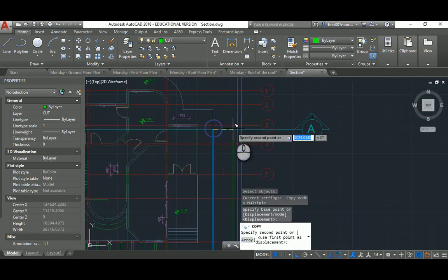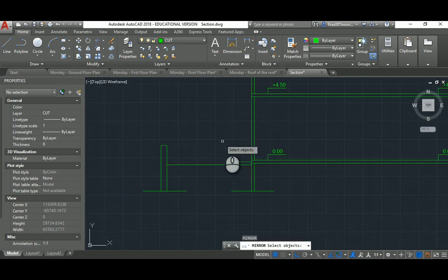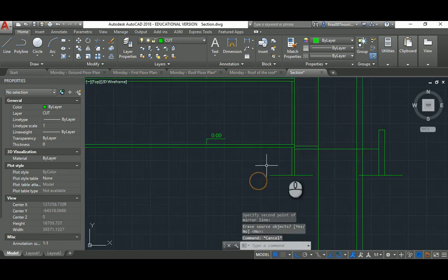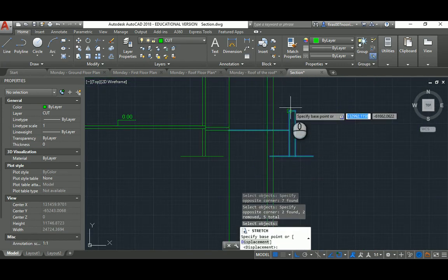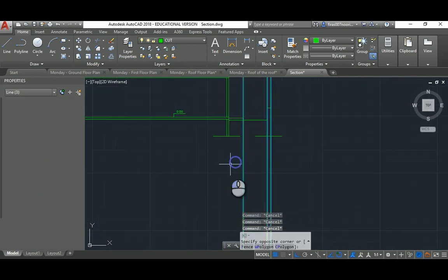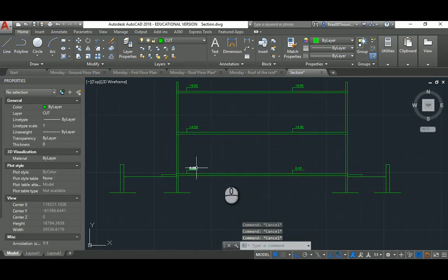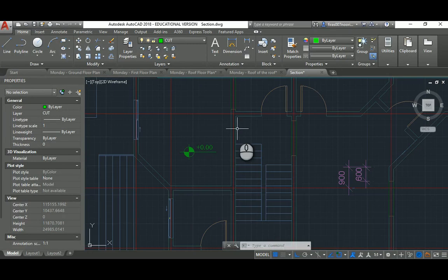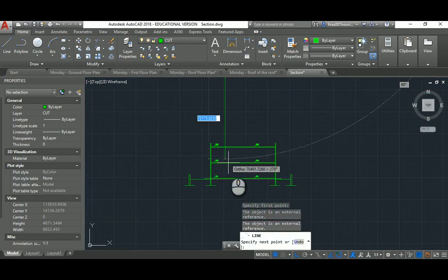And those represent the fence, so just don't draw it again, please. Use mirror, it's a good command. So that's a happy coincidence here, and just push that aside, and that's it. You get yourself a nice mirrored part. So that's again all the section part cut and ready for us. Now that's been done, I'm going to go inside and then draw the partitions or the inside wall actually cut.